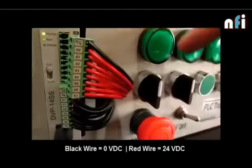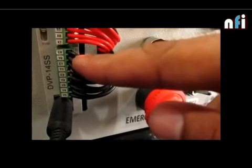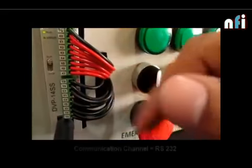Now similarly we have some outputs, and in outputs you can see different terminals like C0 stands for common, then we have Y0, that is the first output, then again C1, second common, second output, third common, and then 4 outputs. So these 4 outputs have a single common that is C2. Similarly this Y0 has an individual common of C0 and Y1 has an individual common of C1. So these are the input output terminals of this PLC.